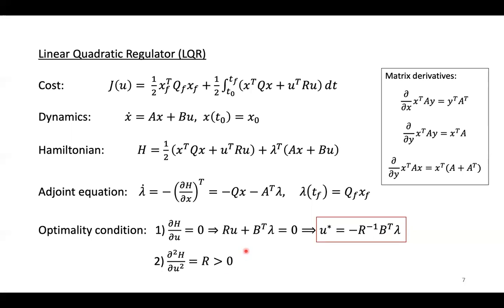So which is why I said in the beginning that R is typically assumed to be positive definite. If not, then you cannot talk about optimality for this controller anymore. And of course, if it is, let's say, positive semi-definite, you cannot even talk about inverse existing. So you really require this R matrix to be positive definite. That's a requirement that you cannot compromise upon.